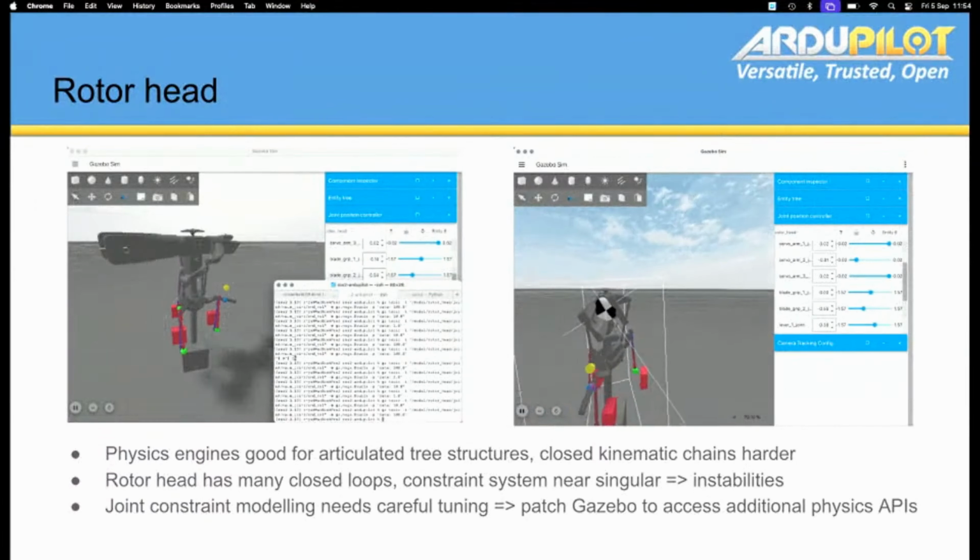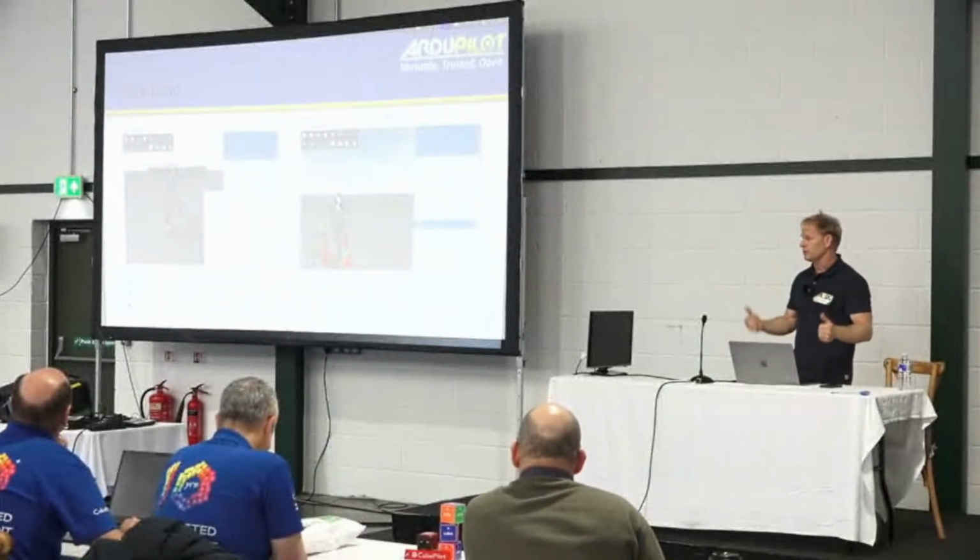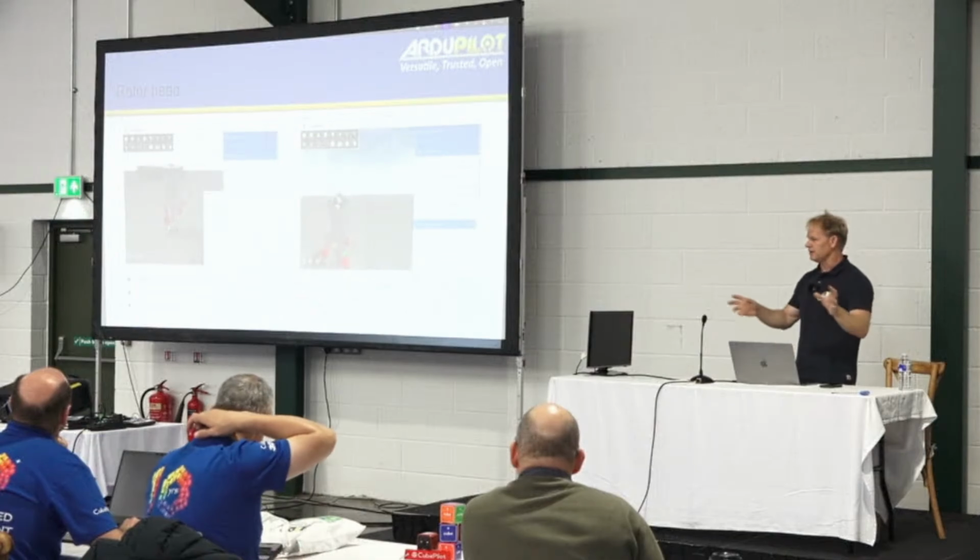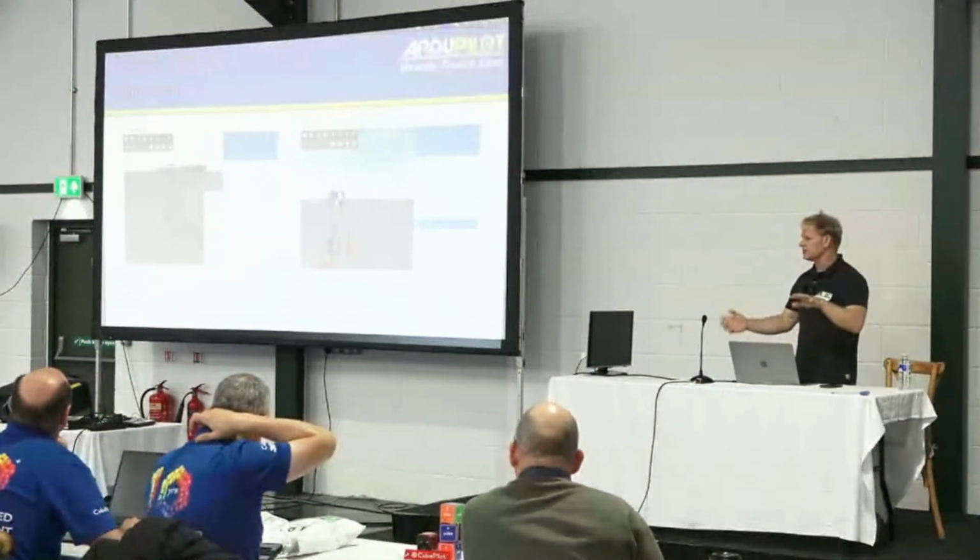And the nice thing about that is that's how we drive a helicopter. We drive it with three servos. We adjust the cyclic and collective on the swash plate with three servos. If you have this, then it's easy to plumb ArduPilot into the rotor head.